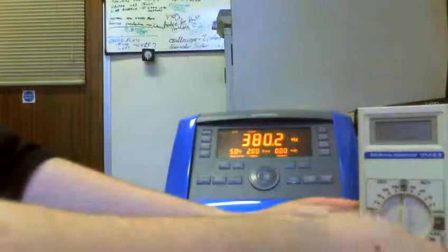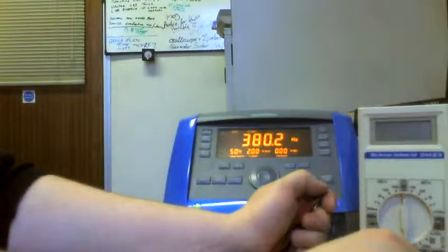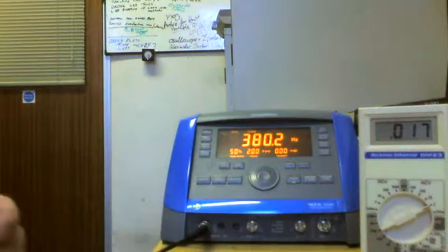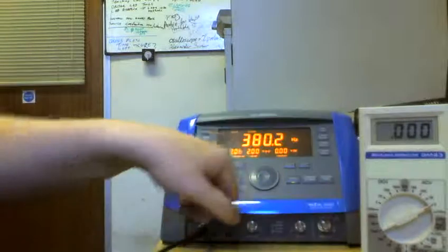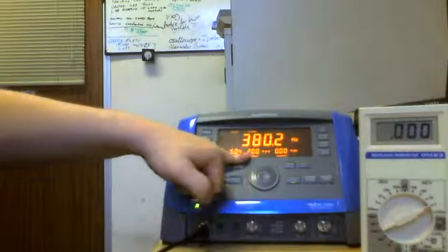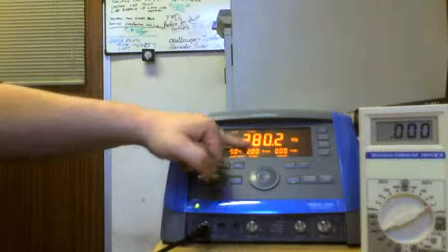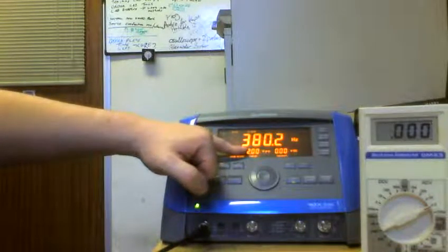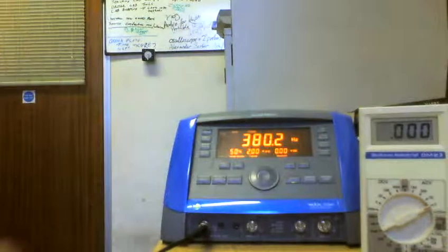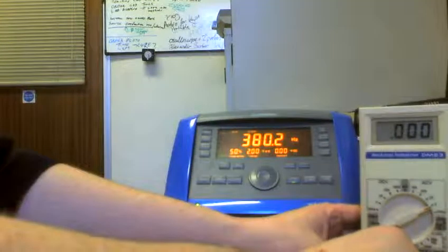If we're measuring an AC voltage, let's switch it to the AC range. It's at 2 volts peak to peak, so we'll switch it to 2. This will be 2 volts RMS maximum that it is reading. So 2 volts peak to peak, half it to get the amplitude, that's 1 volt. Then we divide by root 2 to get our RMS value, so we're looking at around 0.7 volts we should be expecting. It's our DC equivalent if we're measuring RMS.